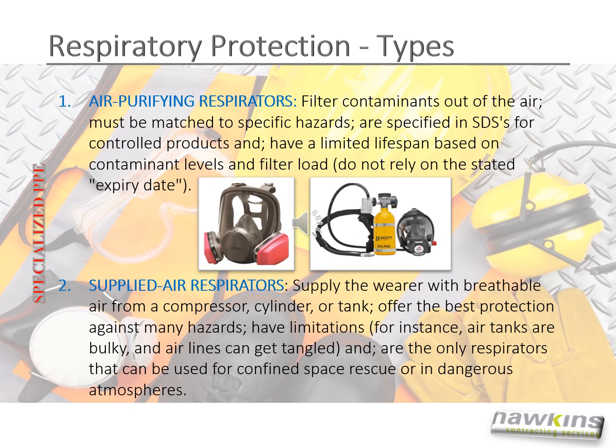There are two types of respiratory protection. The first is air purifying respirators. They filter contaminants out of the air. They must be matched to specific hazards, are specified in SDSs for controlled products, and have a limited lifespan based on contaminant levels and filter load. Do not rely on the stated expiry date.